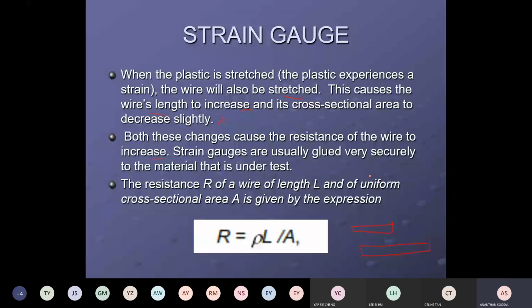Okay. As I said, used for the cracks one. Let's say you have cracks, you put the wire here, the strain here, and connected to op-amp. Okay, so the fine wire here will extend when the cracks... This is the cracks, when the cracks grow. When the cracks grow, this wire will extend.